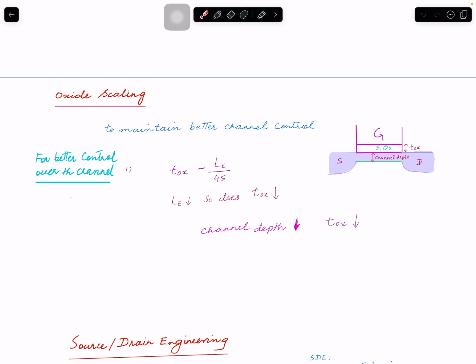And that was really done, if you look at when you reduce the thickness, what really changes? This is a capacitor, right? There's a positive charge and negative charge happens here. You reduce the distance between the two, like in a parallel plate capacitor. What happens? Your capacitance goes up. Sorry, so your capacitance goes down. Okay, when your capacitance goes down because this thing got smaller, your influence here is more. You're really controlling this area more with this voltage.